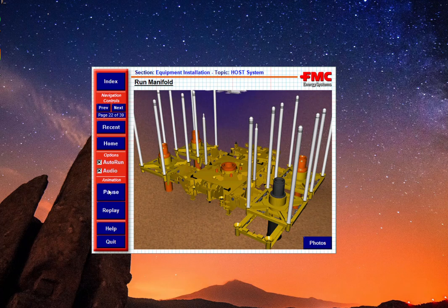So what you do, of course, is cement several wells at the same time, and balance it out so that you don't finish one well on one corner. You do batch drilling on the top in order to make sure that it's level and stabilize the whole template. Now, what they're showing here is that you're running down the manifold later on, but in most cases, the template is complete when the drilling rig comes, and you do batch drilling of conductors.